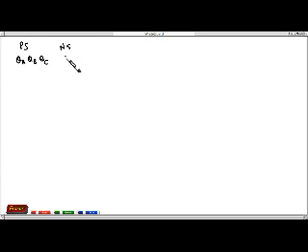The next state will also be for QA, QB, and QC. And lastly, we need to design for the inputs to the 3 flip-flops, which are the DA, the DB, and the DC.